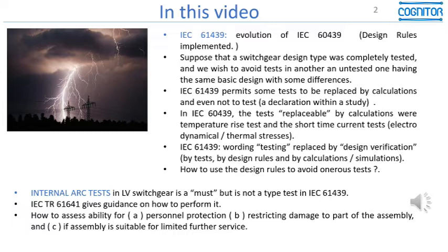In IEC 60439, the tests replaceable by calculation were temperature rise tests and short time current tests. In IEC 61439, the wording testing is replaced by design verification. And this is the new thing.